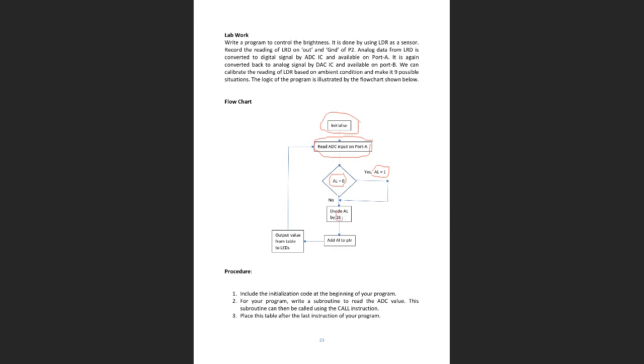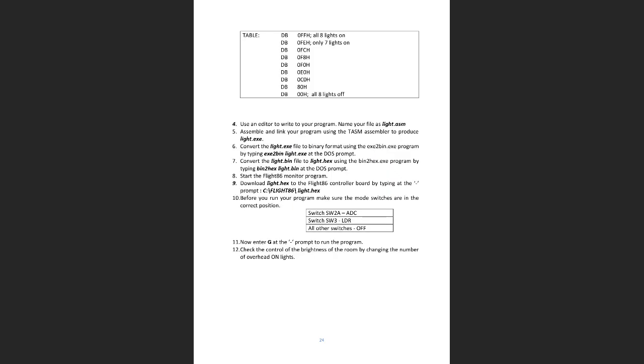And then we will divide it by 16, because to get 8 different values, because we have eight different combinations of lights. Then this ADC value, after dividing by 16, we will add it to the pointer. The pointer value is for the different light values. I mean, the pointer value for this case is 0. What is the offset value?